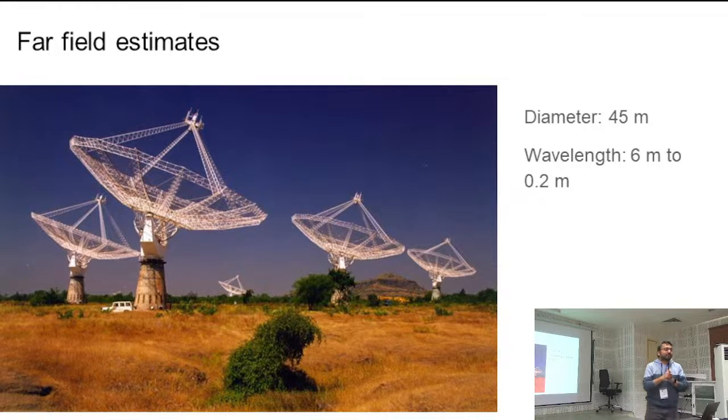Anyway, so yeah, there are ways to measure the beam. The question lies in how and to what accuracy. One thing one has to keep in mind is when making any of these measurements, you can't be arbitrarily close to the antenna because your very presence will affect and completely change the radiation pattern. And that's simply because you are in what we call the near field. So you are also a dielectric electromagnetically. So when you are near, you are also part of the antenna.